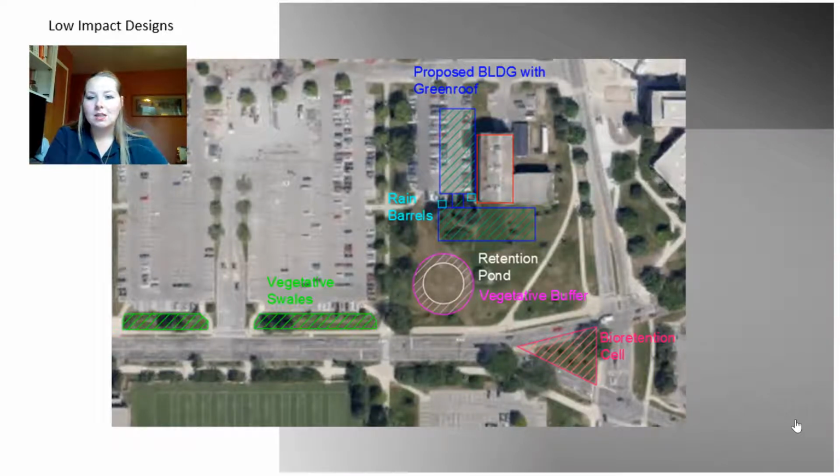As you can see, the proposed new branches of the building are shown in blue, and there is a green roof proposed for the roof. Green roofs are another variation of a bioretention cell that have a soil layer laying atop a special drainage mat, material that covers excess percolated rainfall off the roof. This design would be used to facilitate drainage from the roof and may be coupled with various rain barrels.